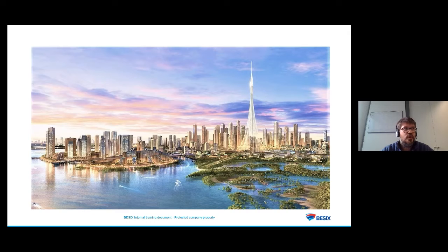Another challenge is that this concrete has to be pumped, but after that it will be cast in walls more than 3 meters thick. The problem is that it's going to generate a lot of heat, and as we have a lot of cement, because it's a high-strength concrete, it is going to generate a lot of heat. So we also have to deal with that. For the moment, it's just testing for this project. It's not built yet, but anyway, the mix design is there, and it was a lot of work, of course, to be able to produce this.